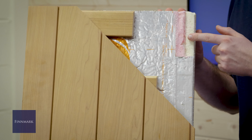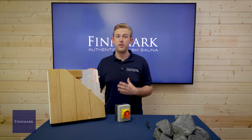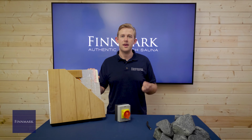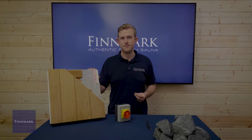Once secured onto the walls, the joins are foamed up using an expanding foam adhesive and sealed with a high-tack aluminium vapour tape. Once you complete this, you should have a fully insulated and fully vapour-sealed environment, with the only penetrations being any windows or doors and the ventilation points.